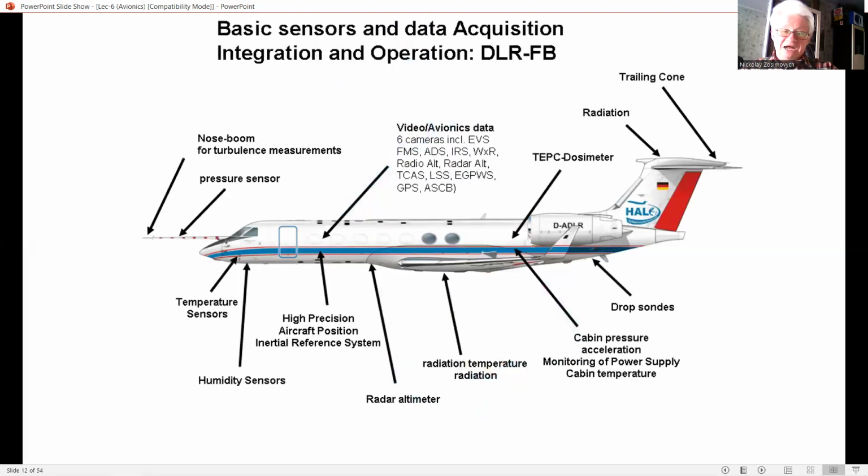The incidence term from the airstream sensor can be blended with the pitch rate error term, and the gain coefficients of these terms adjusted as higher angles of attack are approached. This enables the angle of incidence to be kept within the safe limit whilst maneuvering at high angles of incidence, or angle of incidence limiting.